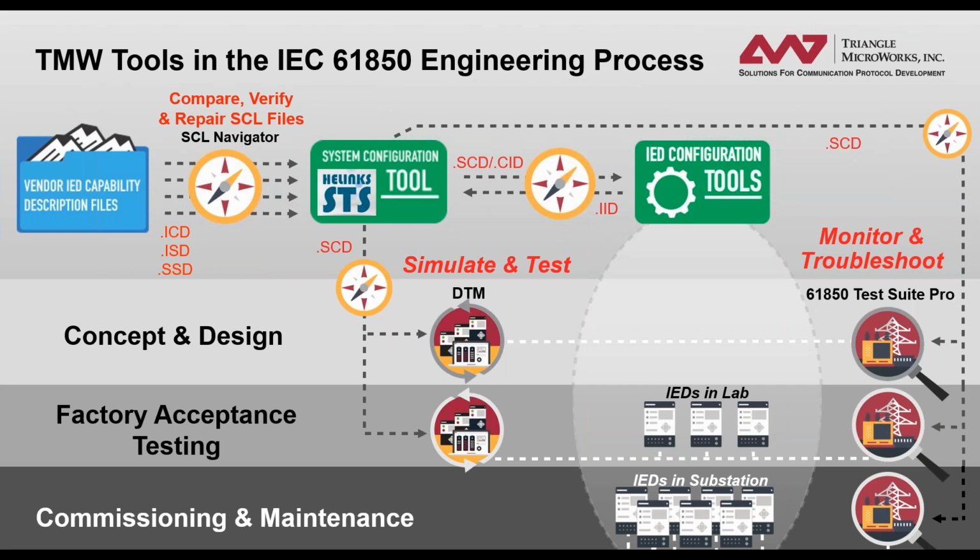Okay. Next question. How can it be indicated where the subscription can take place in the ICD? Okay, there are two aspects of that. The subscription as such is configured in the SCD file. We didn't look into that in detail, but we configure the IEDs that are supposed to receive the GOOSE message. And in the IED, we can configure with an XREF the signals that we receive on the particular logical nodes.